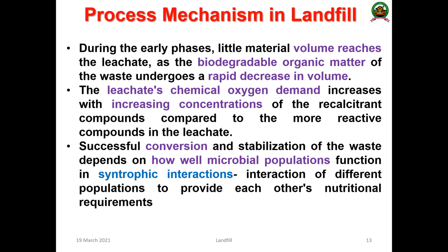Okay, so during the early phase, a small material volume reaches the leachate as biodegradable organic matter. How will it happen? The biodegradable organic matter of the waste undergoes a rapid decrease in volume. Then the chemical oxygen demand of the leachate will increase with increasing concentration of the recalcitrants or xenobiotics, compared to the more reactive components in the leachate.